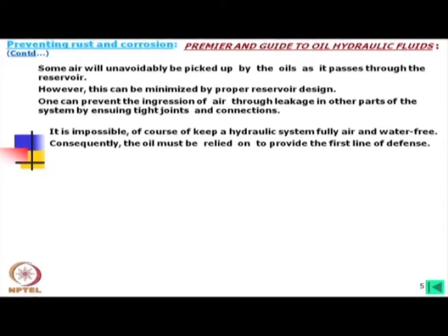Now, say water, how does the water get mixed up? You see, hydraulic components are exposed to the atmosphere. Say for example, the rod end of a cylinder is exposed to the air. Then some moisture goes inside, and in that moisture there will be some water particles which will be mixed with the oil.